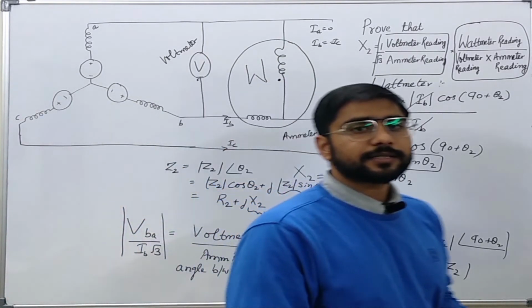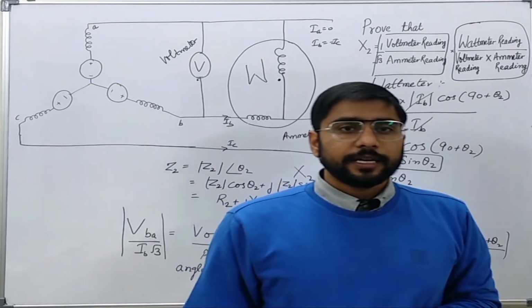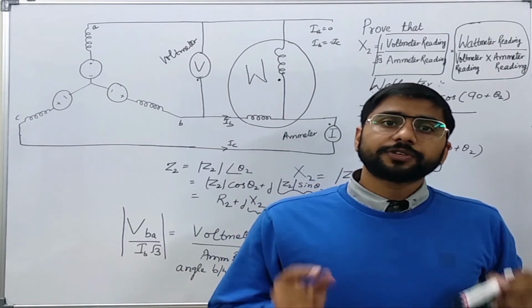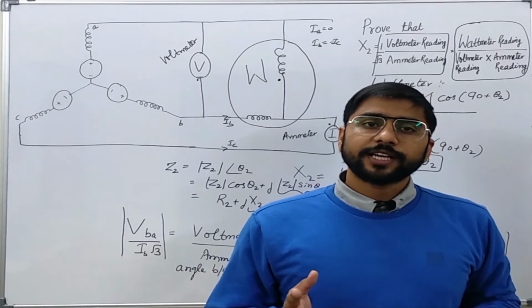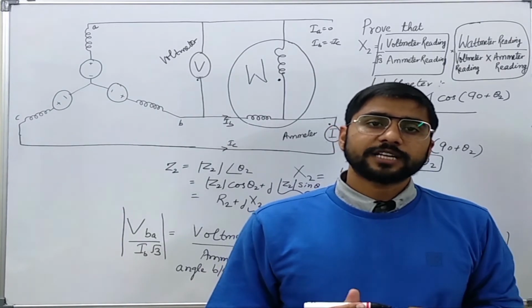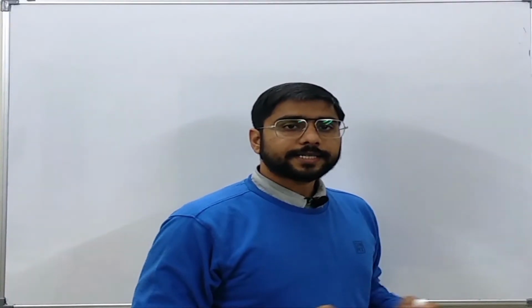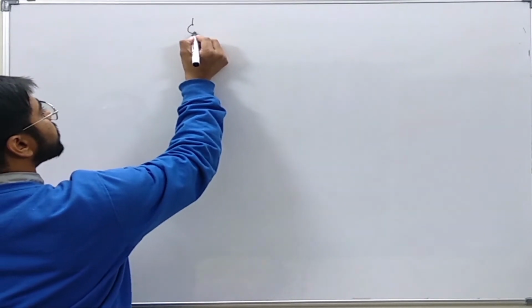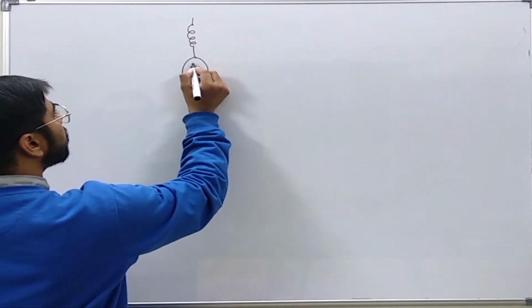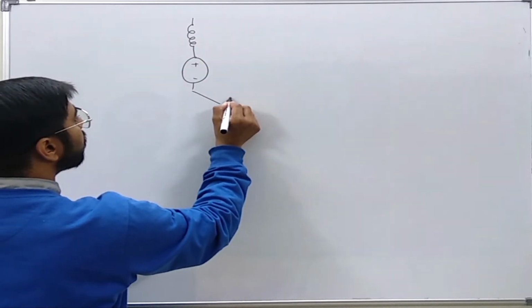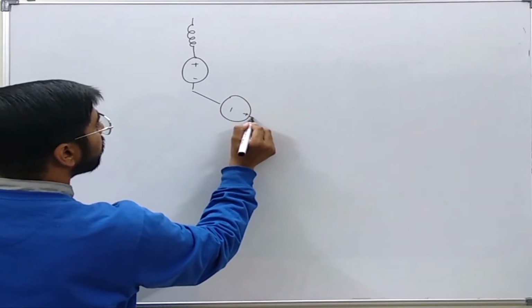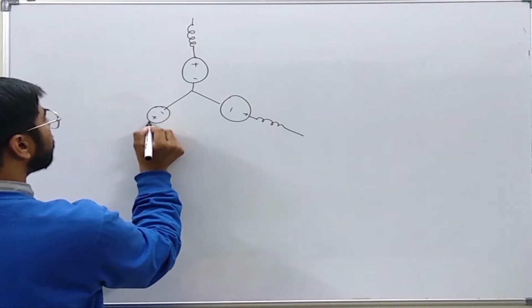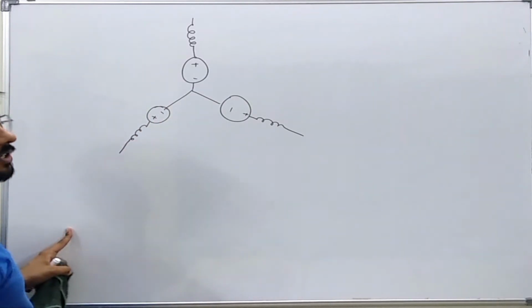Now in the next slide we will prove that in one of these scenarios, a single line to ground fault can be more severe as compared to a three-phase fault on the system. Let us see what that scenario is in the next slide. Now let us take a case that there is a synchronous generator which is solidly grounded.